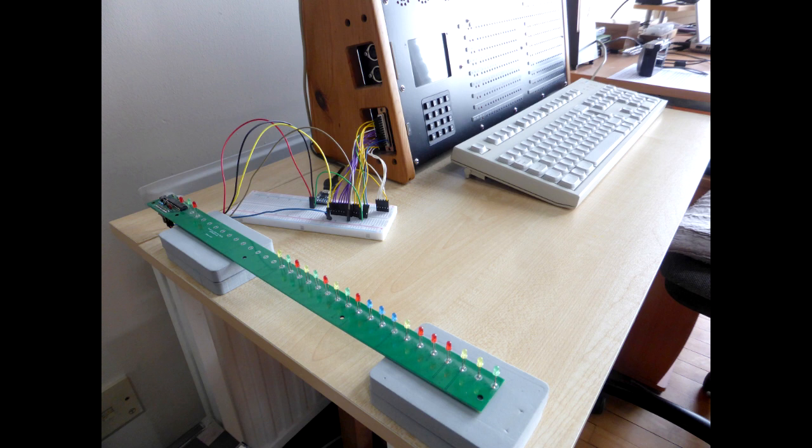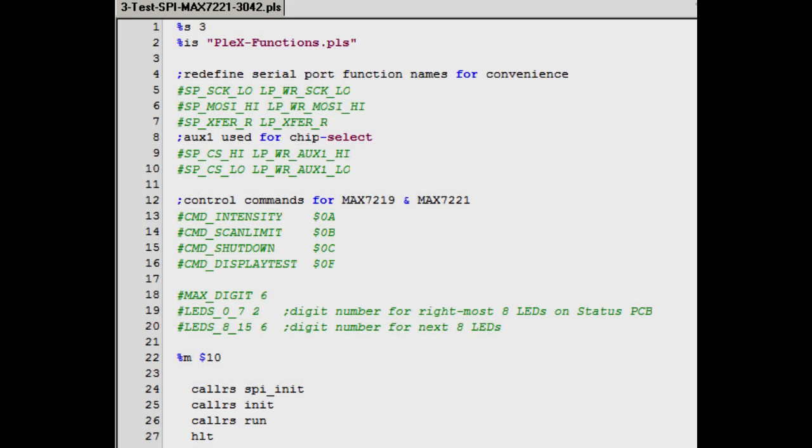The 4-wire protocol uses the 4th signal as a data or command identifier, or DC, for the transfer. Either way, spare aux-out pins can still be used for any of these functions. Later on, I'm planning to demo a 4-wire display which uses both DC and reset. Okay, back to the LED demo.